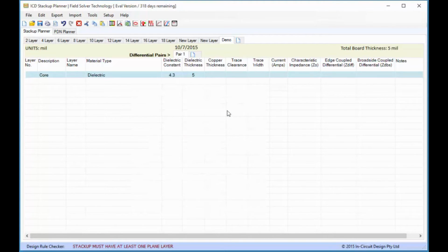And a core material is a hardened material. It's a dielectric material, so it's not conductive, and it usually has a copper on the top and on the bottom. Actually, not usually, it always has a copper on the top and a copper on the bottom. And so once they have this material, they'll etch off the copper based off of whatever pattern you have, and depending on what layer it's going to represent on the top and on the bottom.